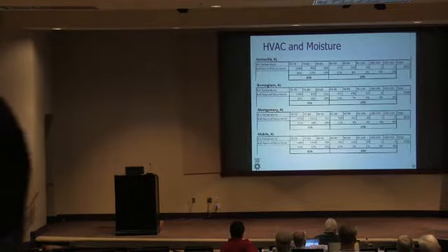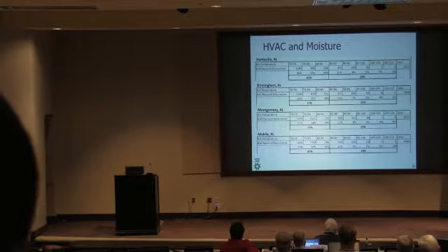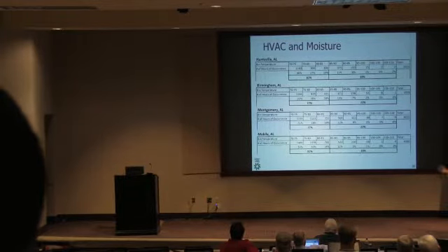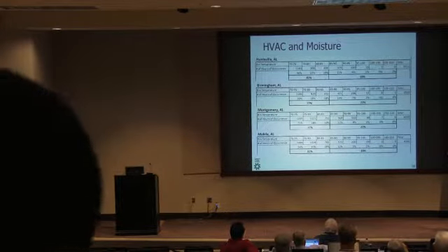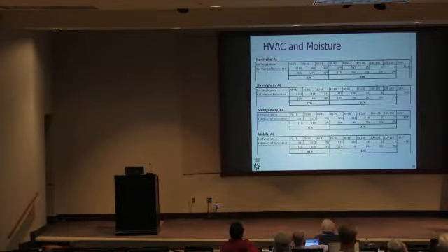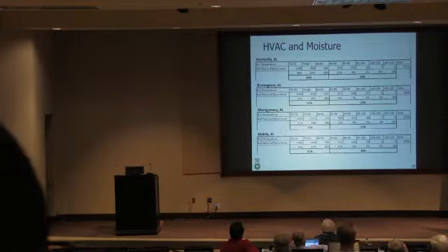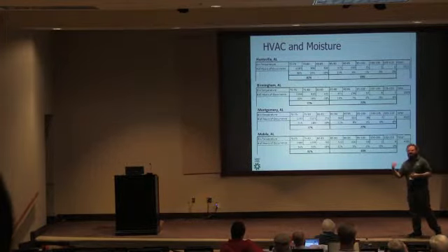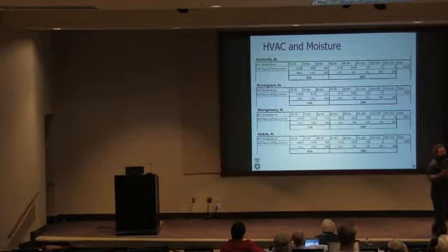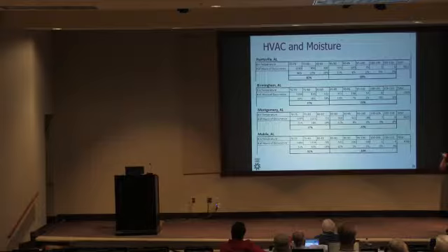And if the reason we're doing all this stuff to our homes, spending this energy, doing this air sealing, doing this insulation, doing more efficient systems, is because we care about being able to walk in and have it 70 degrees, perfectly comfortable year-round, it ain't the heat, it's the humidity that we're really trying to deal with. And oversized equipment, improperly sized equipment, load calcs that aren't done, loads that are not reflective of what's actually installed in the home, they're not going to provide good comfort because they're not going to dehumidify effectively.